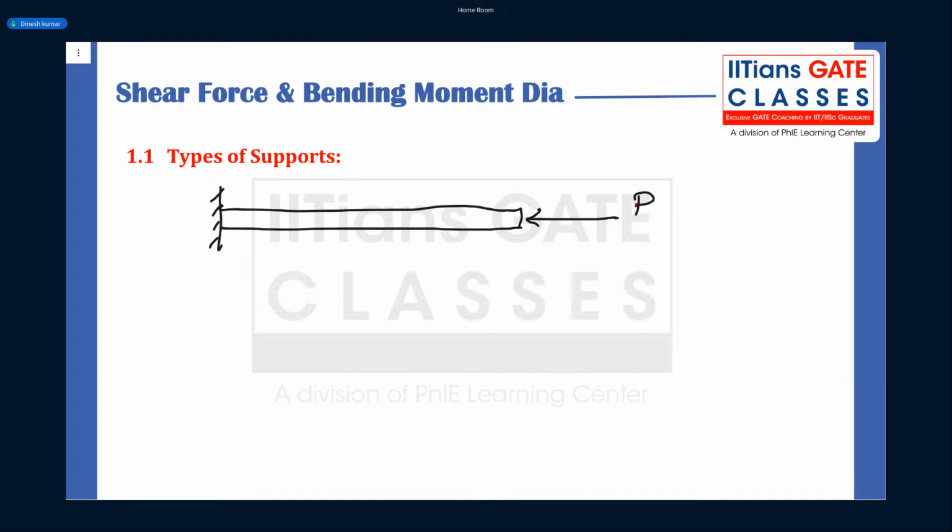Column structure. Okay. So column means not necessary to be vertical, or I say in other way, a structure need not always be vertical to fail under buckling. I can have a structure, Mr. Arakji, like this, and it is subjected to compressive load. Okay, it may buckle, it may fail due to buckling.